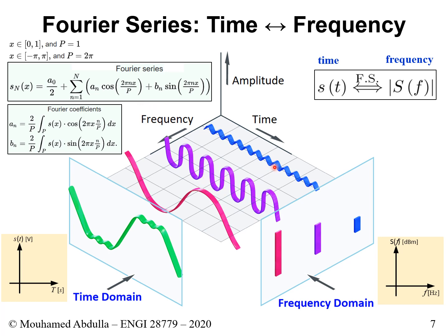When you look at it in the frequency domain, especially if we only look at the magnitude and don't look at the phase, shifting does not matter. So whether you look at a sine wave or a cosine wave, it will look the same. You just need to know at which frequency it happened and what is the value of this power. Okay, so I hope that makes sense. We'll do some problems, and you'll do some problems as well in the assignments, and that should help you. Let's move on to the next slide.